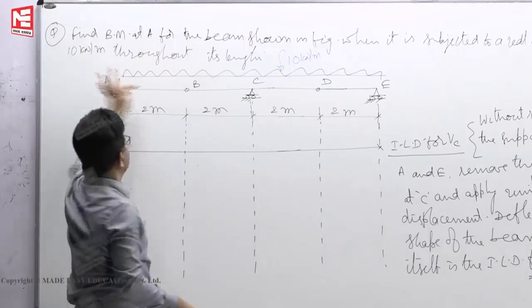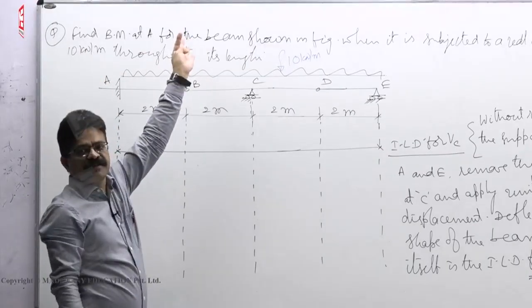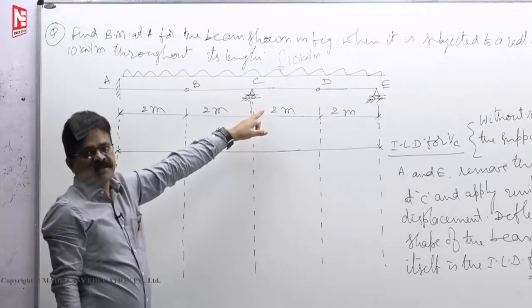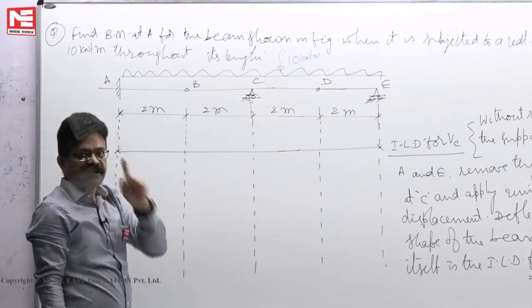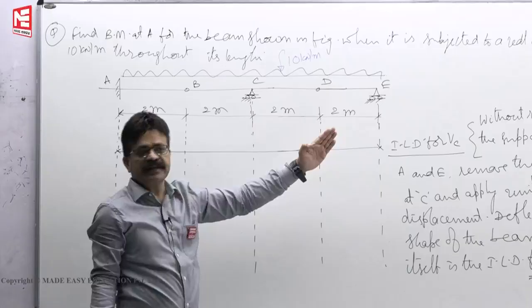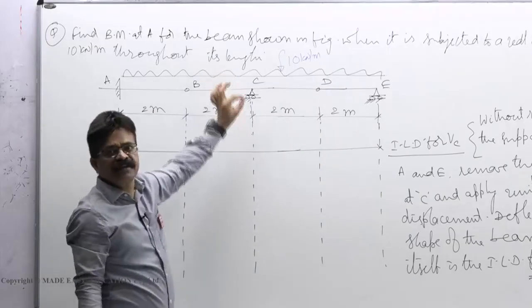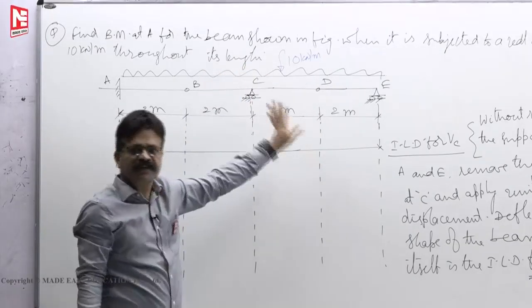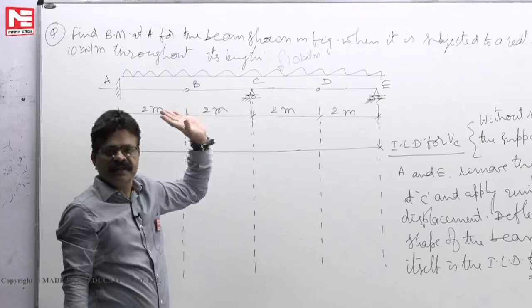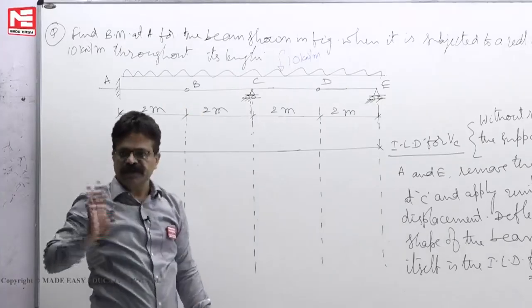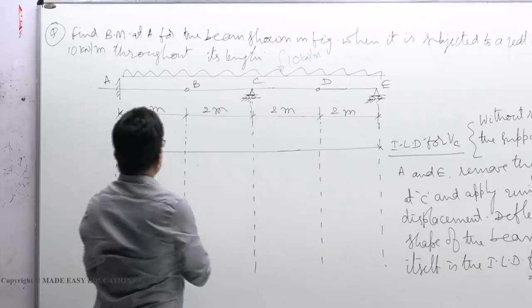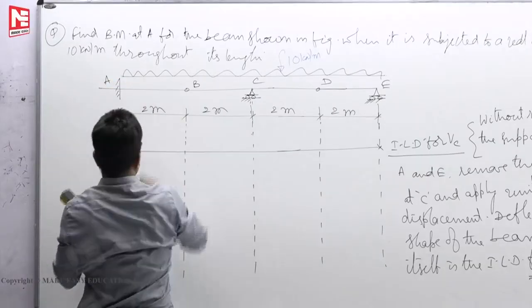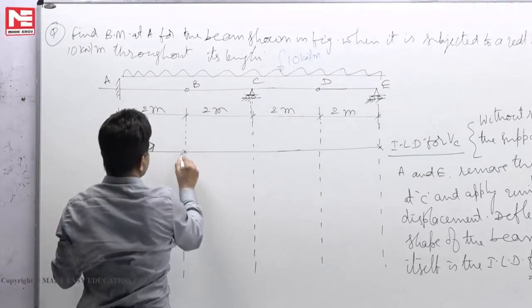But in a statically determinate structure, influence line diagrams are straight lines, because if you remove the support here, it becomes an unstable structure. When you displace it, it will only undergo rigid body translation or rigid body rotation, means straight lines only. As a mechanism, it will displace. So, once I fix it here, it has no choice, it will not go up or down.